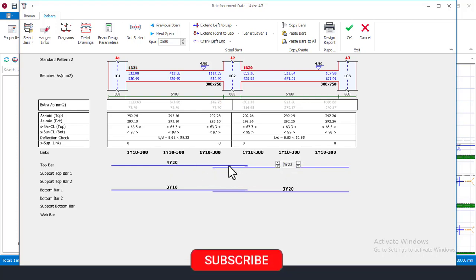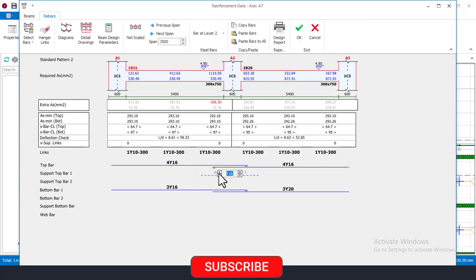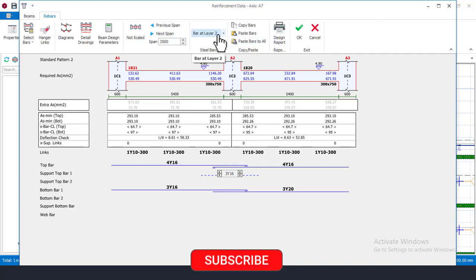Okay, this is okay to have straight, but like I said, you take the cost into consideration. So having 4Y20 all through this top here is more expensive compared to having Y16 and then coming here to put just three bars here and call it layer 2. So this is cheaper compared to having 4Y20 all through.